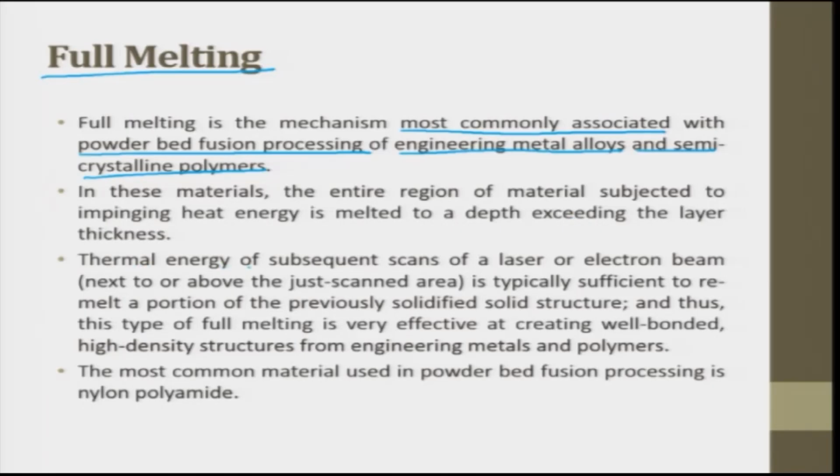The thermal energy of the subsequent scan of the laser or electron beam is typically sufficient to remelt a portion of the previously solidified structure, and thus this type of full melting is very effective at creating well bonded, high density structures for engineering metals and polymers.